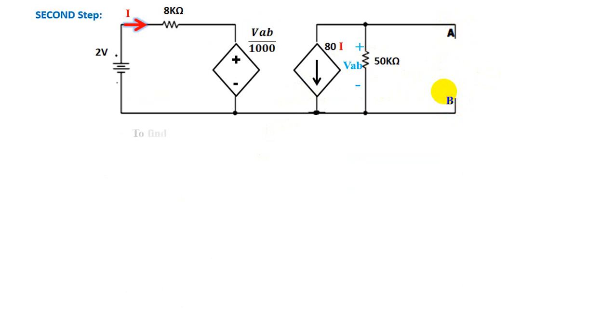Now the second step, to find ISC or to find IAB. In Norton theorem, it's better that we use IN instead of IAB. For short circuit, I'll always find the current going down, and you can see what I am doing here. Why am I eliminating 50K? Now you can see that these two branches, this is your first branch and second branch, appear as if they are in series, parallel or star delta. They are in parallel, and this resistance